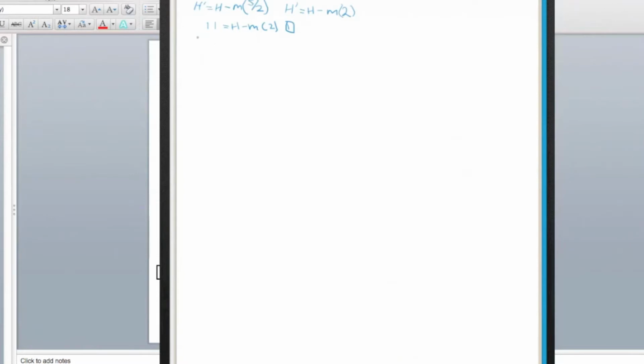The other equation that we use here is that for flow. If you remember, flow Q equals K A. K is the permeability, which I didn't actually write down, but I'll give it to you right here. And A is the area of the conical surface, since we're using a simplified conservative method.